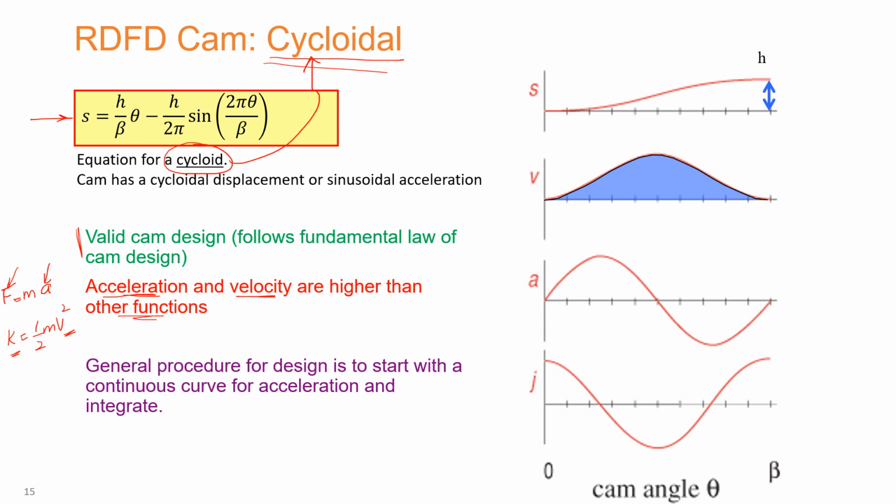So with this realization that we have gradually improved the CAM design procedure, in a sense that we started from a naive CAM and then moved on to a simple harmonic motion, and then observed its behavior and tried to find ways to further improve it, eventually reaching the cycloidal CAM design, which is a reasonable, acceptable CAM design for us.